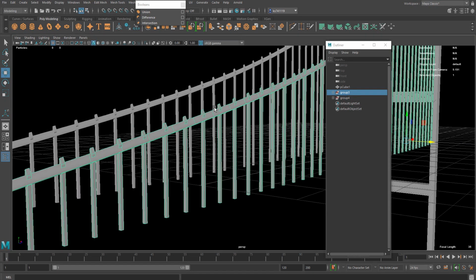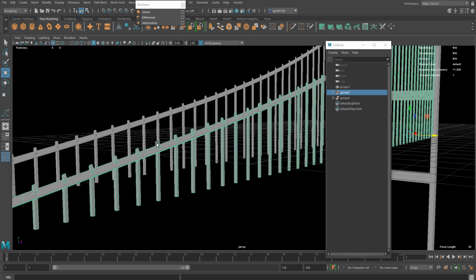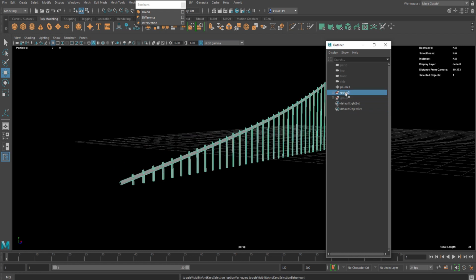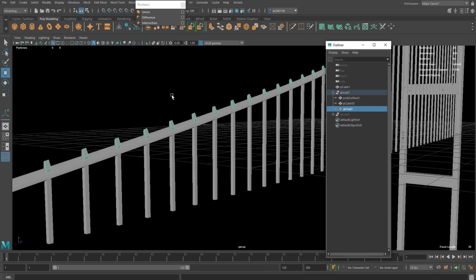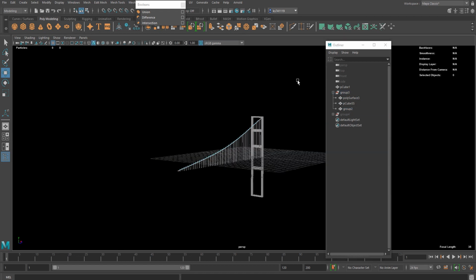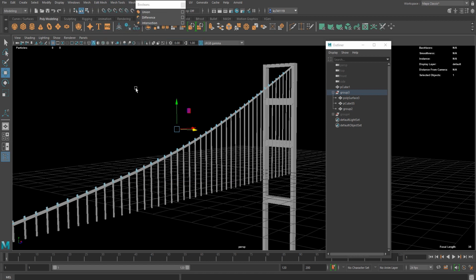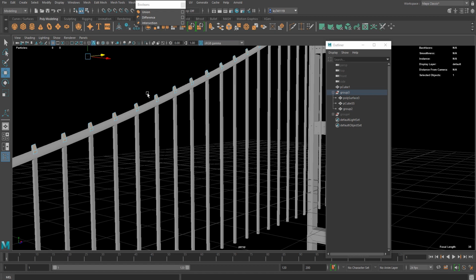But before we go, maybe it's a good idea to replace those lights, because it's easier to work with fewer meshes. So I'm just gonna hide the other group and select the light object and go to the edit mode, select everything, make sure you detach all of that with everything selected.